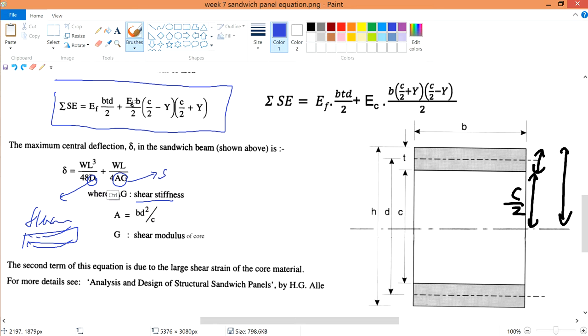So it's like a ratio between your weight, your forces applied against its certain length. So it's like a moment because it's force times perpendicular distance. Alright, so your length is actually the perpendicular distance. So it's a moment against the stiffness of the thing. So if the moment is larger, you'll need a larger stiffness to keep the deflection low. So if your moment is low, then I think you get what I mean.